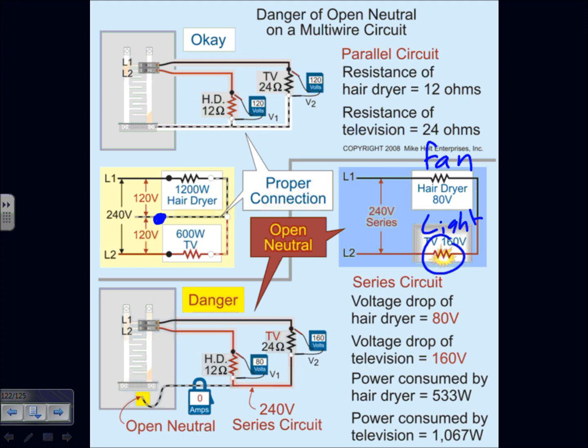So when you go to the panel right here, it would be easier to unscrew this wire here, the hot, than doing this. If you unscrew this one, the neutral, you just burn these equipments. Imagine your plasma TV here and your garbage disposal here. Burn both of them, and the circuit breaker will do nothing. What happened, guys, as you understand, is these equipments are rated for 120 volts, and all of a sudden, you put them in series.